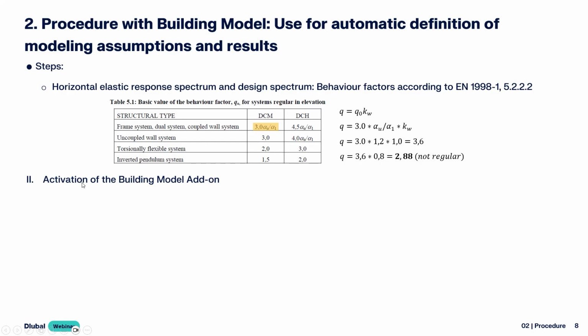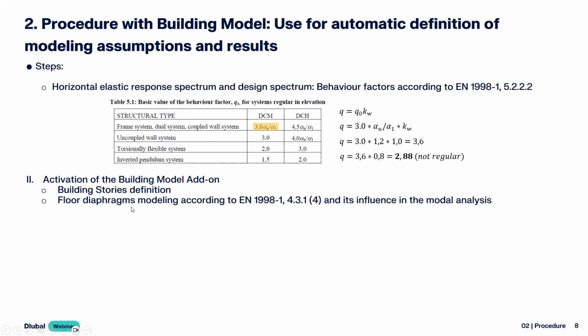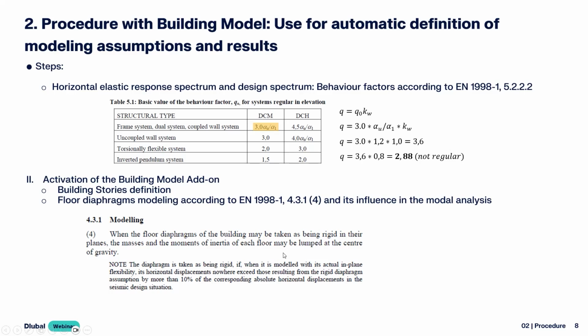Now we can make the activation of the building model add-on. Before running our response spectrum analysis, I'm gonna make the building stories definition and the floor diaphragms modeling according to section 4.3.1, and I want to show the influence of this on the modal analysis. This floor diaphragm modeling makes reference to a very famous assumption in seismic design or seismic analysis, the so-called rigid diaphragms.